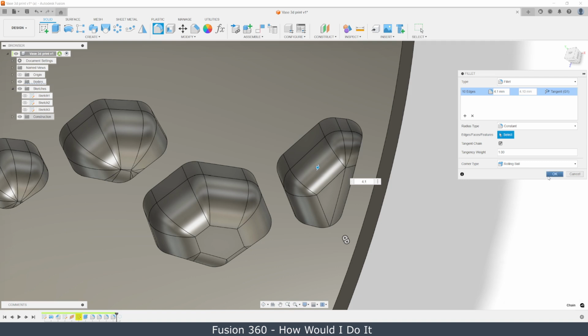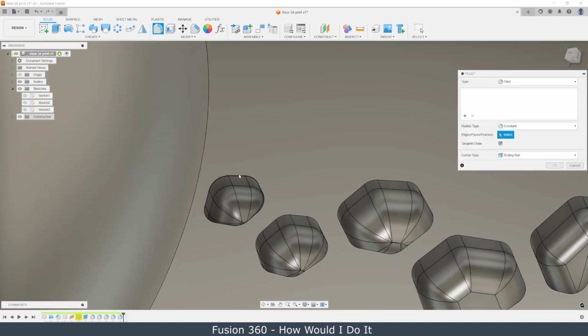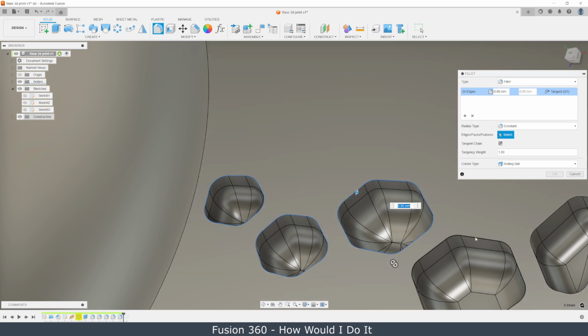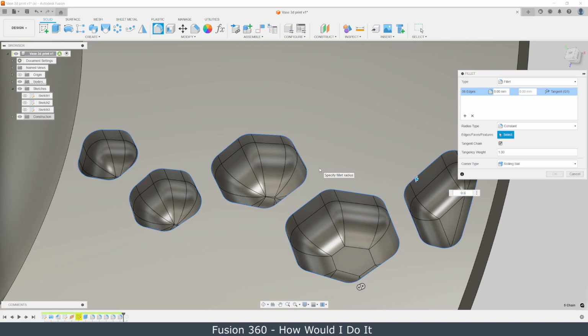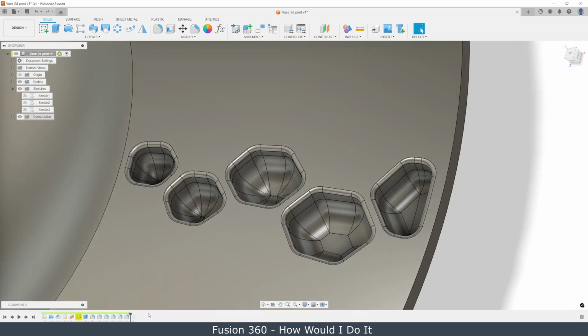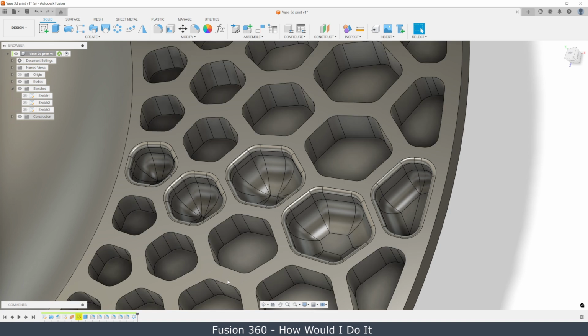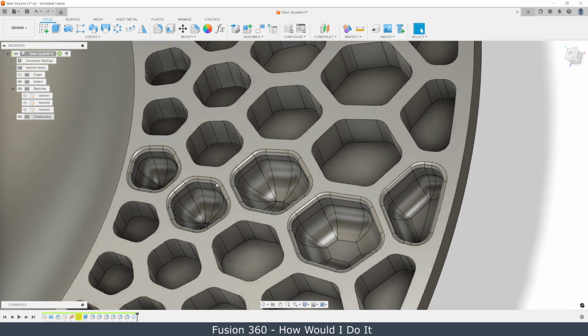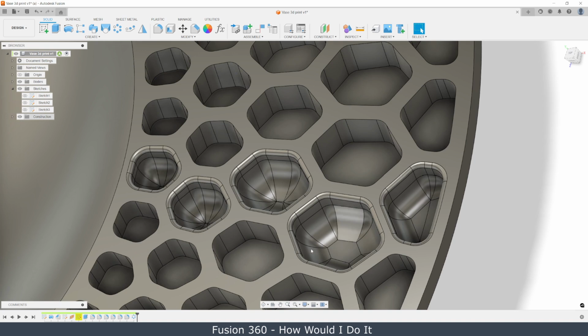4.1 seems okay. Now add fillet up here for all of these edges, small fillet radius. 1, let it be 1, okay. Now go to the end of the timeline, and we will see how it will look now. So this is how it looks. Now we have these fillets applied only on this one feature.